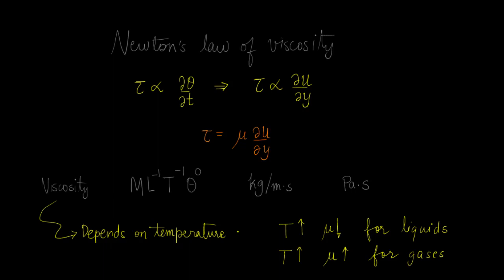The viscosity depends strongly on temperature, and this is quite an important physical parameter because, for example, in a motorcycle engine or any engine, there is a certain amount of lubricating oil that exists in the crankcase. When the engine is running, the engine starts becoming hot, and so the lubricating properties will strongly depend on how the viscosity changes with temperature. For degraded oils, which have not been changed for quite a while, the viscosity does not change appropriately with temperature, leading to inefficient performance of the engine, which is one of the reasons why engine manufacturers ask you to replace engine oil now and then.